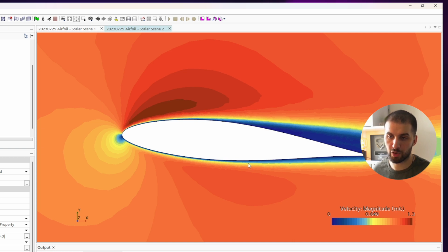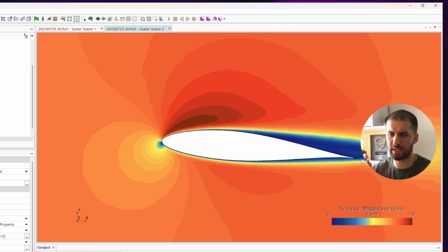Of course, if you want to compare to experimental data, what you could do, for example, is plot the points of the experiments, and there are some tools where you can kind of go to a paper and define the X and Y axis, pick all the points, and it saves them in a MATLAB format or like in a CSV file. Then you can overlay the simulation result of maybe a line that you have defined across your profile, and kind of have virtual probes inside of your simulation, virtual sensors, where you can validate your simulations with experimental results if available, obviously.